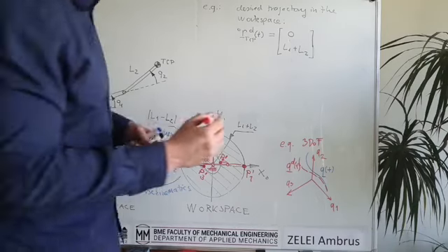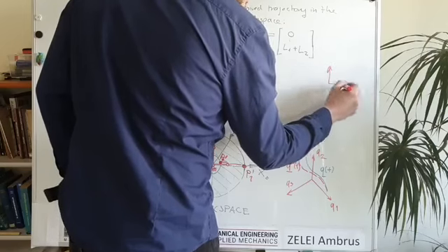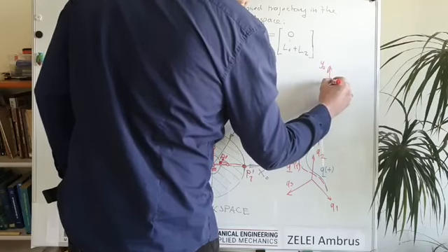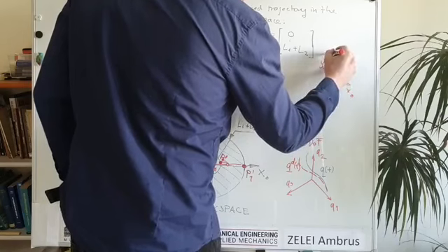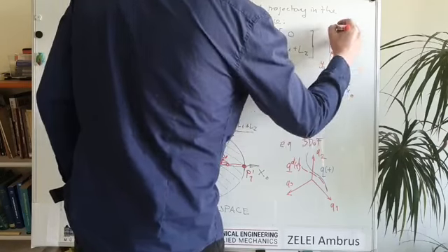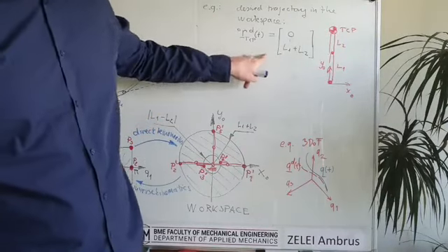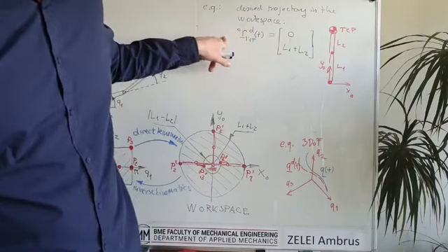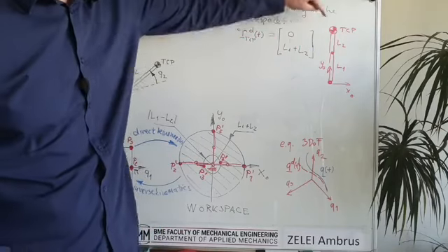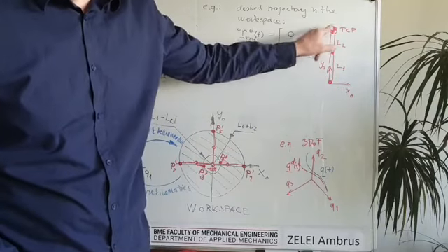So we can just draw the corresponding figure. So this is x0, y0, and the robot looks like this. Okay, this is L2, this is L1, and this is the tool center point. And if we formulate the desired trajectory in the workspace, then we say that the tool center point will be here at x0 and y equals to L1 plus L2.